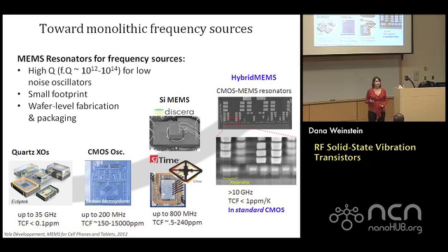are what make it really attractive. The problem is that these are bulky off-chip components, and that limits these things to maybe tens of megahertz in frequency. You can lock these in some phase lock loop to your chip, get up to 35 gigahertz frequency or so. So there's a lot of things you can do, but having that separate chip, having a bulky off-chip component can be a major limiting factor, particularly when you're scaling